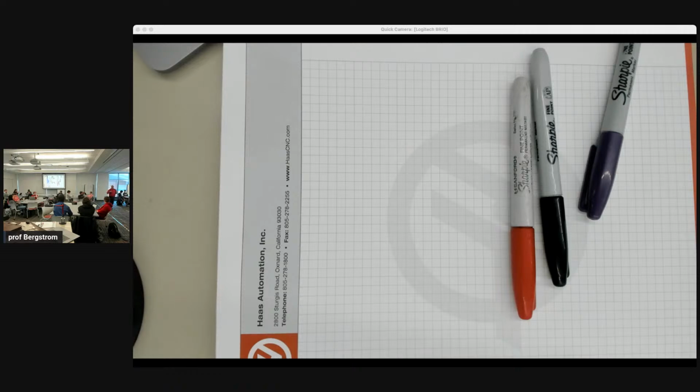I think I asked in class yesterday who had done a tool change at 5%. That is super slow, right? So we don't want to do that. You can change that rapid speed at any time during the program. As it's moving, you could say, all right, it's doing a tool change, let's go to 50%. Finish the tool change, then just go back to 5% because we're worried about the coming down part, if you're worried about it.